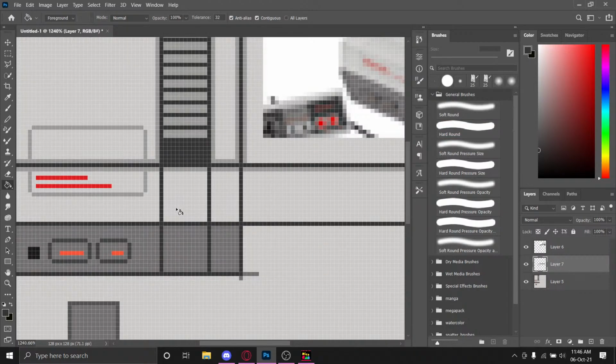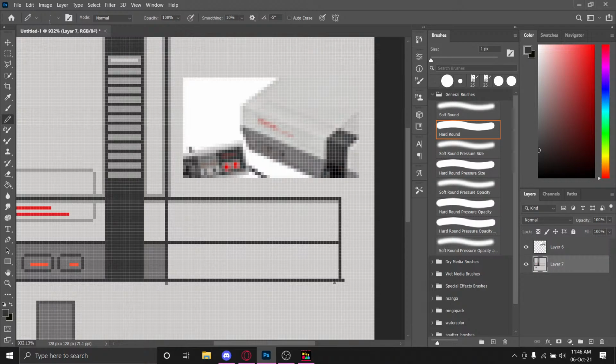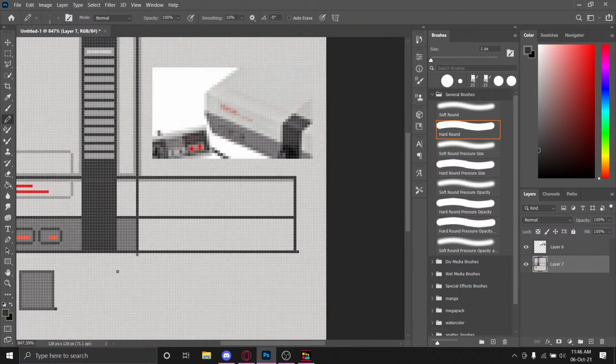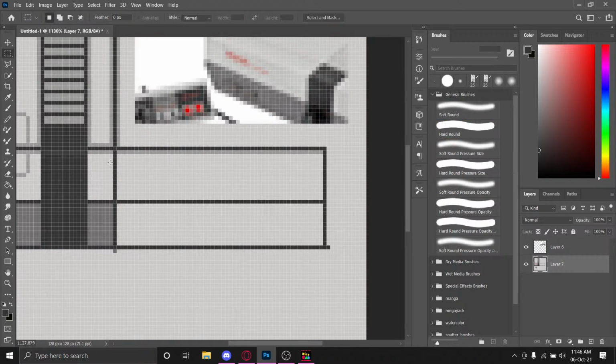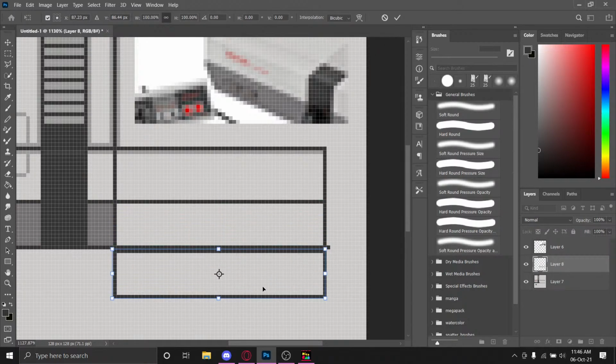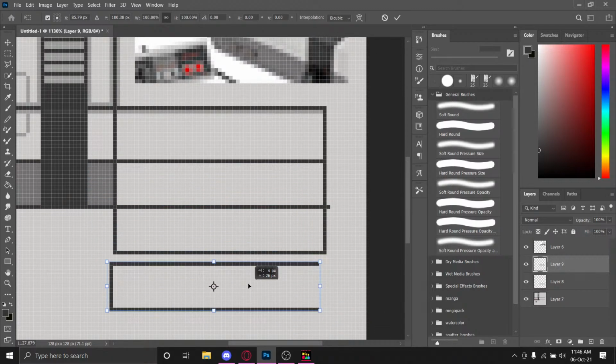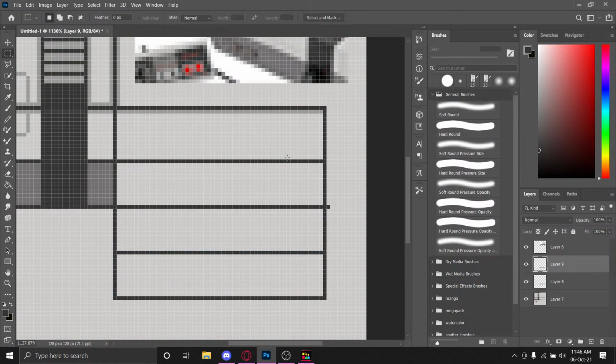Use my, oh sorry, my bad. Use my fill tool to fill these in. Right. And again use my pen tool to extend this on the bottom, and in a similar way I'll just copy this for the other side. So we need a total of 4 of these. Control C, Control V, Control T to transform and add it over here. I can Control V, Control T again to copy paste it again and paste it again.